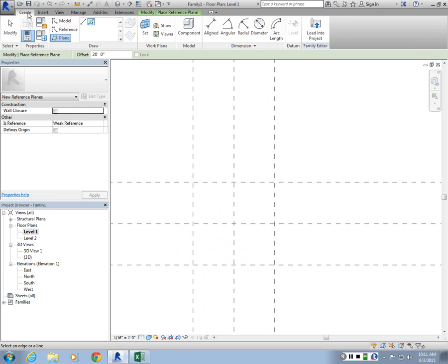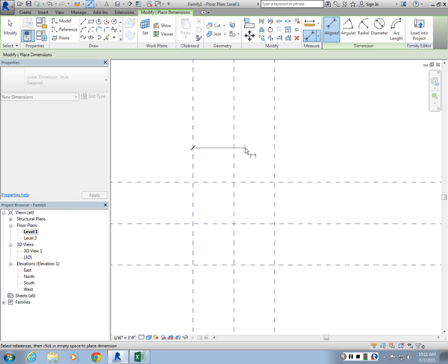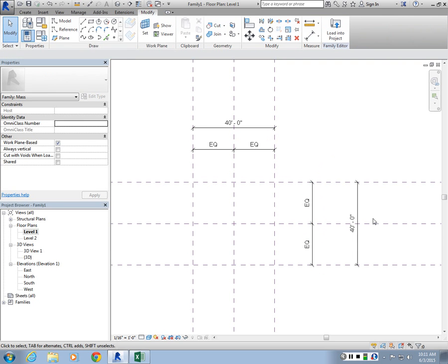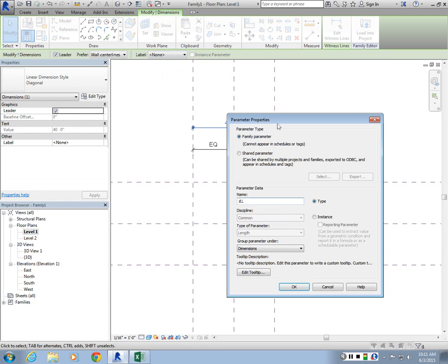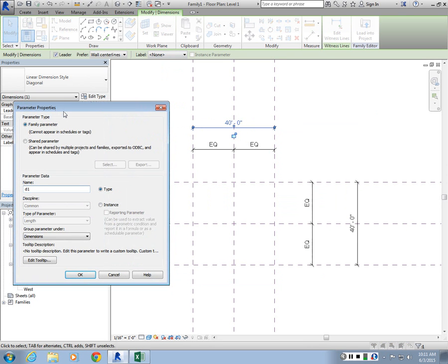And this thing I'm going to do, so the central axes are going to be fixed. So we first want to do the offset, and then give an overall dimension for the vertical and horizontal parameters. Right, so these two are going to be equalized. The horizontal is going to be, let's call it, I wrote them on the board, so D1 and D2. You can give them any type of parameter name if you want, like width and depth. I'm going to do D1.